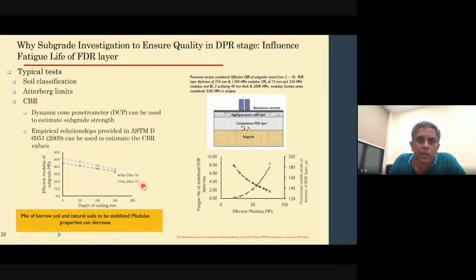First, let's say the OMC, as per JMF, the optimum moisture content, is 11%. Now, that is based on lab studies. In the field, the soil already has some amount of moisture in it. Let us say the in situ natural moisture content is 4%. So if I need an optimum moisture content of 11%, out of that 4% is already there on the site.